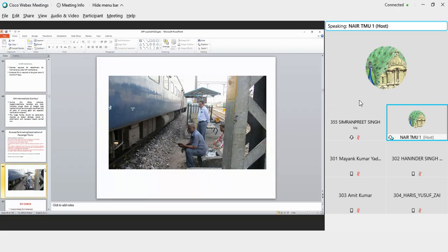A large number of accident cases of passenger trains which have happened in the past have been attributed to defects at the last rolling in, rolling out examination points. Assuming the train has failed after 200 kilometers of the last rolling in examination, and you find that an unusual sound came or a jerk came or a spring flew off, then this rolling out point would be caught. Partner, only 200 kilometers earlier you had examined the train. Why were you not able to catch this defect? So this is called a rolling in, rolling out examination.